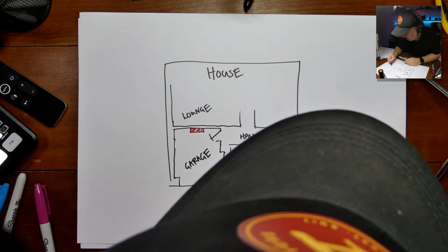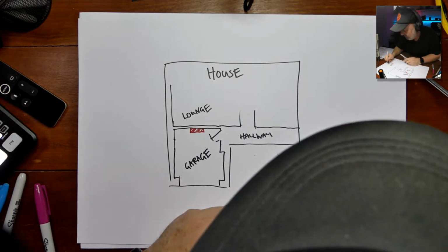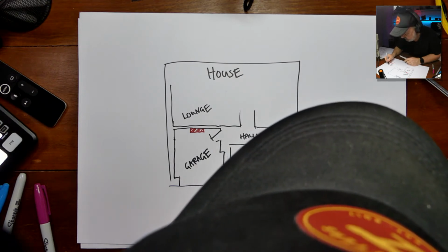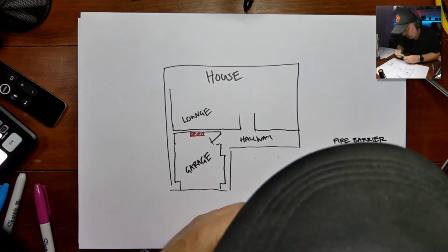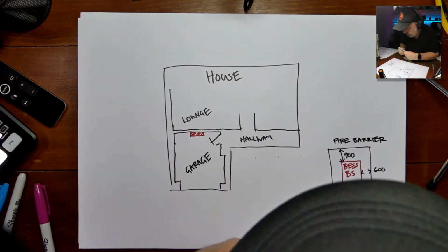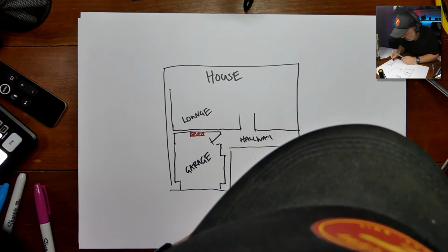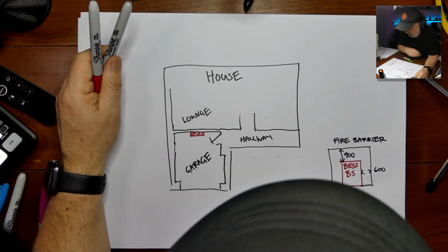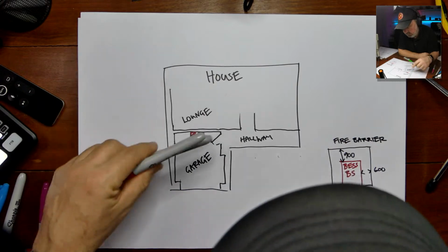And that fire barrier, it's not actually called a fire barrier, it's called a barrier for the protection against the spread of fire, can be made of brick, concrete block, terracotta tile, cement sheet, or a material rated to AS 1530.1, which is a non-combustibility rating. So that area around here is the fire barrier that would be required.